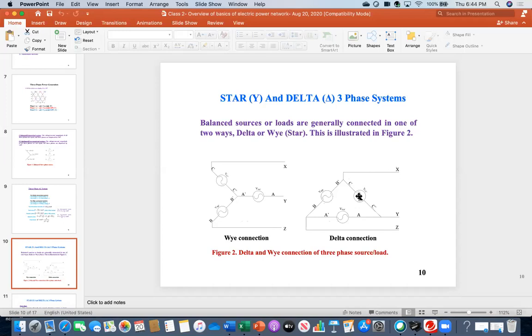And what is the consequence of that? Gradually these coils will be heated up, and at some point might be burnt. So in this case, the possibility is that because of the unbalance, this coil itself might be burnt out, and the system might be fully damaged. In the other case, these coils typically do not burn out. There are examples that these neutral lines from time to time get overheated or overloaded because of those additional currents and get disconnected. And if it is disconnected, then immediately you can fix it.